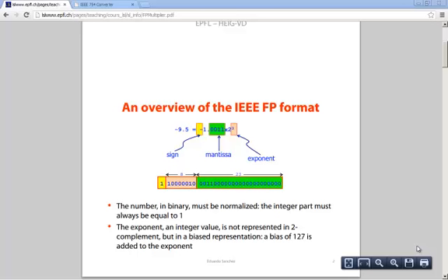I will show you the implementation in VHDL. This implementation took into account some constraints due to the assignment. One of the constraints was that the multiplication of the mantissa must be a sequential multiplication instead of a parallel multiplication. We implemented both parts. The parallel multiplication was implemented using the for generate statement in order to generate a cascade multiplication scheme, and the sequential multiplication is the next one.